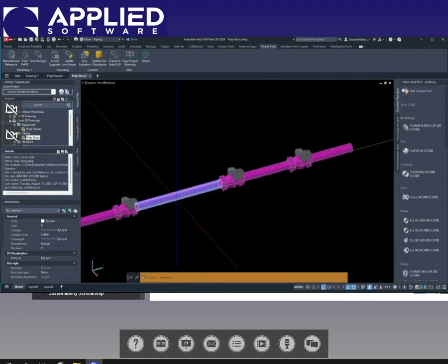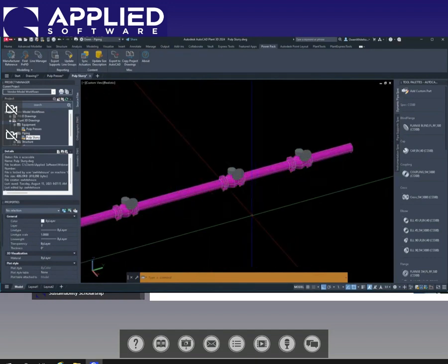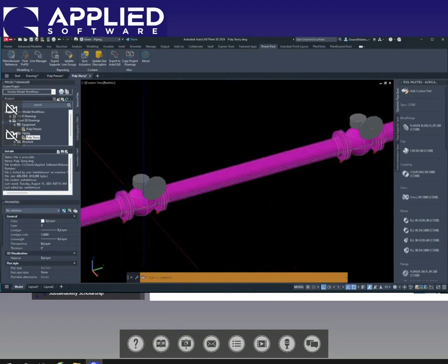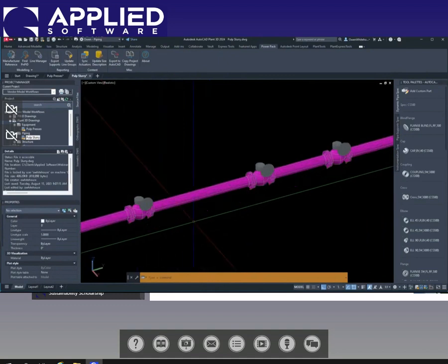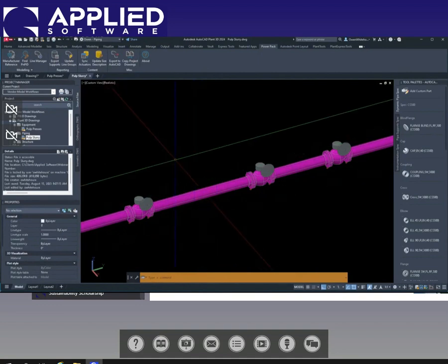So it's kind of a simple way to do it, but it really does work well. And I've seen this used to the extent where the entire valve body is inserted as a reference, including the bolt sets and everything, because sometimes you get those with a vendor reference. And you can do that and show a really high level of detail, but it doesn't have to be permanent, and it's such a simple switch out to just swap that XREF and be able to change those files. So kind of a neat tool.